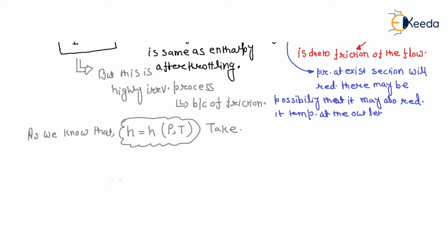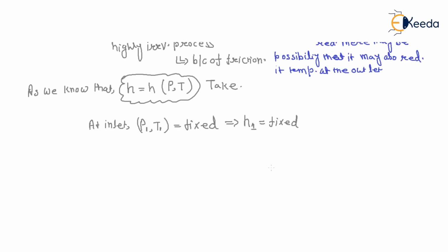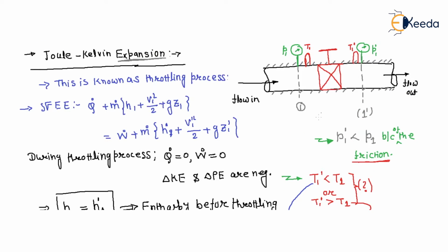So if we fix the quantity at inlet, P1 and T1 are fixed. If P1 and T1 are fixed, then the corresponding H1 is fixed, right? So if H1 is fixed by keeping pressure and temperature constant, that means a fluid which is flowing...